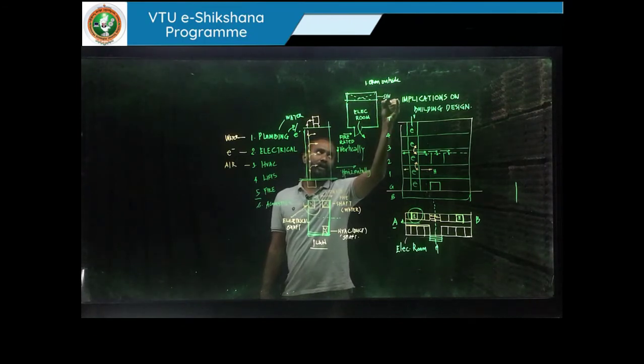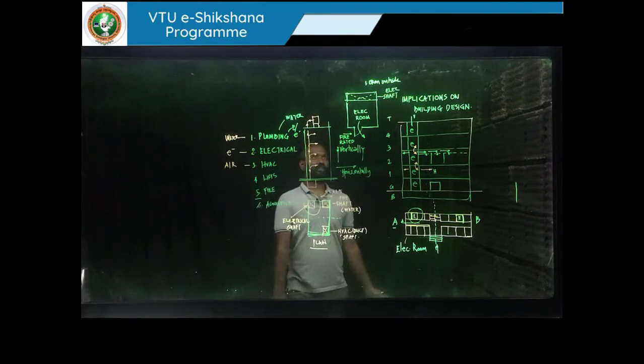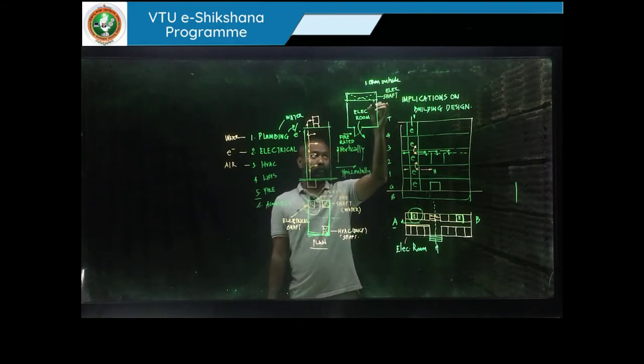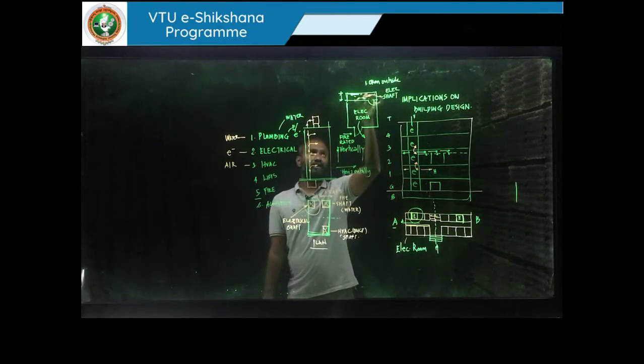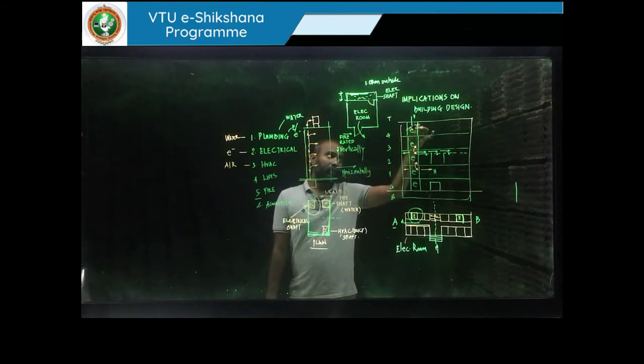This is called your electrical shaft, which will again have a door, depending upon the design, opening outside for somebody to inspect, and this is good enough for somebody to walk in. So this is where all your bus bars, rising mains and all that will be. So this will have a series of wires on several cable trays and bus bars, communicating with each other floor, right?